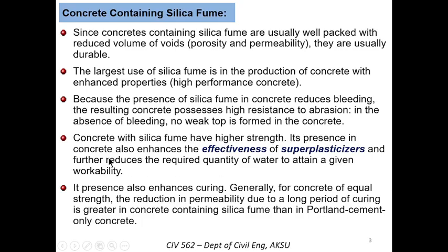Its presence in concrete also enhances the effectiveness of superplasticizer. So silica fumes are usually used with superplasticizer, and because of this combination, they reduce the water requirement. So with a little water, you can achieve the required workability. Its presence also enhances curing. Generally, for concrete of equal strength, the reduction in permeability due to a long period of curing is greater in concrete containing silica fumes than in Portland cement concrete only.